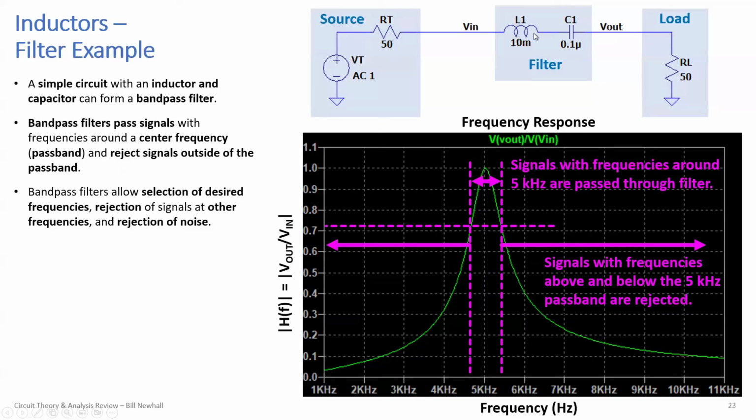As you increase in frequency, you know that the inductive impedance increases. So that magnitude gets big. It's like adding essentially a big complex resistor here, and that's going to cause less of a voltage across the load. So as you increase in frequency, you would get a lower voltage across the load. As you decrease in frequency, the magnitude of the impedance of the capacitor increases, and so that's going to reduce the voltage across the load. Okay, so that's why you get this characteristic.